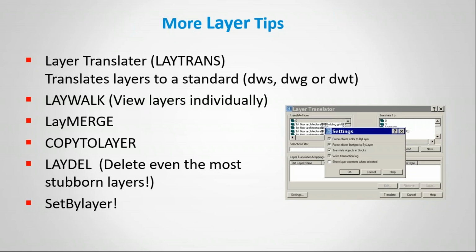Now, there are 2 layers you cannot delete. If it was a live audience, someone would yell them out. You can't delete 0, and you can't delete Defpoints. Those guys are going to hang around, although I have heard that there are ways to get around it. You can delete Defpoints, but we're not going to talk about that today. All right, so that's important to know.